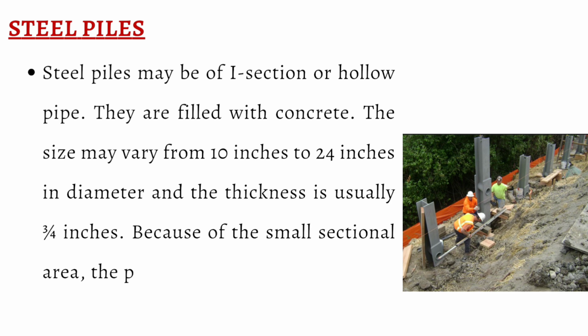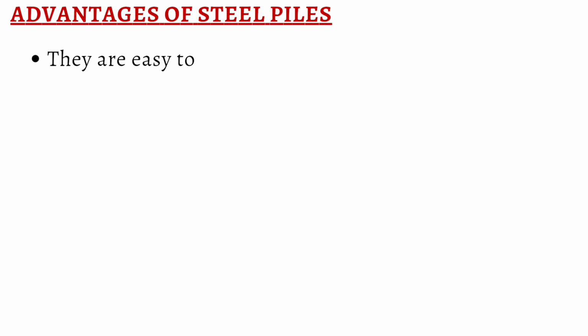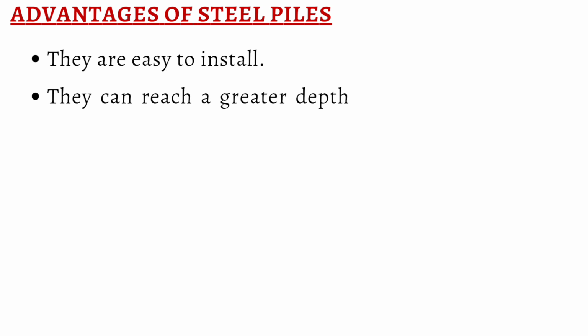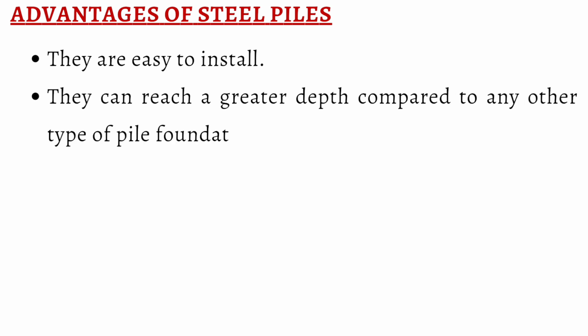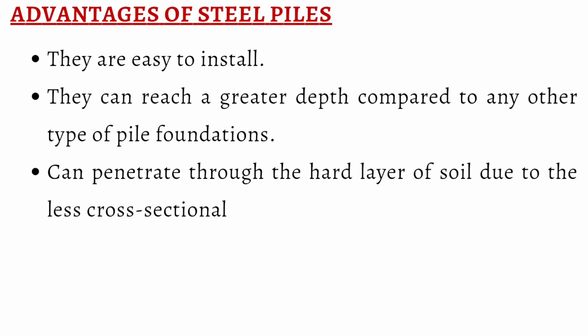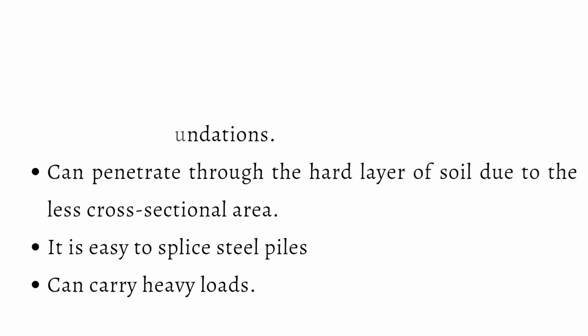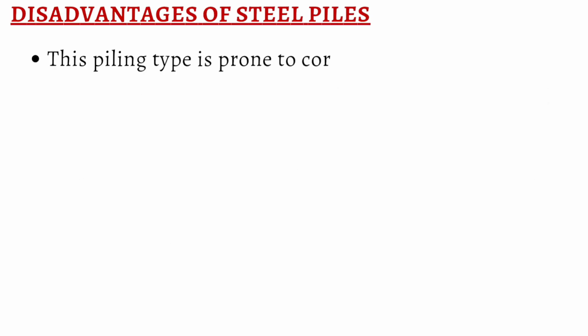Disadvantages. In this type of pile foundation, installation requires careful supervision and quality control. It needs sufficient place on site for storage of the materials used for construction. It is difficult to construct cast in situ piles where the underground water flow is heavy. The bottom of the pile may not be symmetrical. If the pile is unreinforced and uncased, the pile can fail in tension if an uplifting force acts.